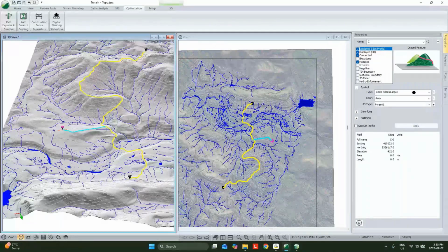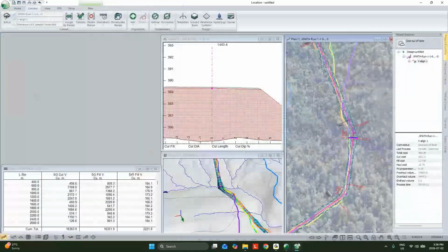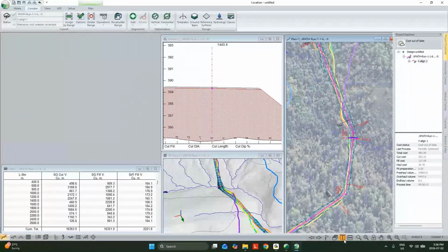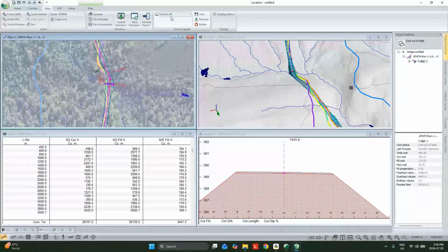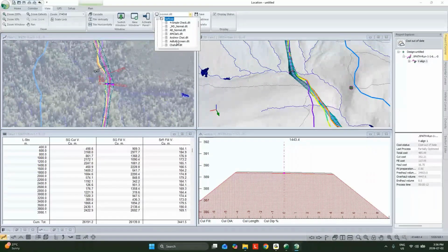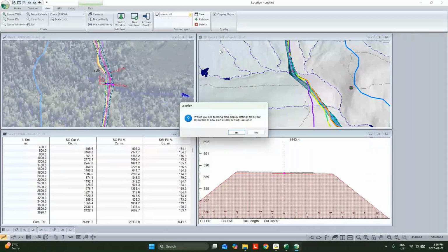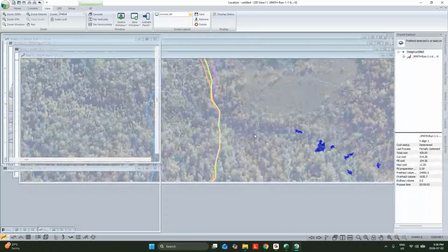The last question: can you adjust the road prism to account for overland sections versus balanced sections? And if so, how do you account for the distance from borrow locations? This is a long question, so I'm going to keep going for a second. For example, it appears that the lower portion of your road crosses a low-lying floodplain, which may have to be overlanded using ballast. Using a balanced road through that section could underestimate the costs.